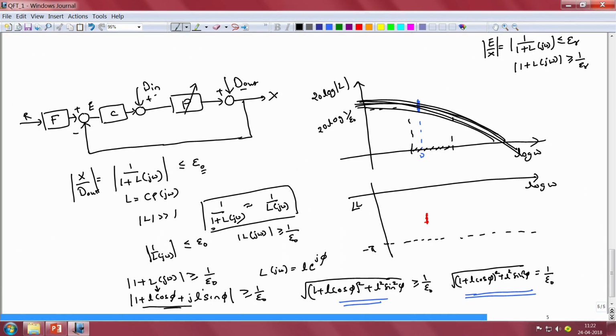The same thing also happens when we are looking at the phase characteristics. So, the nominal phase characteristics of the plant might have a single curve, but when there is uncertainty associated with either the pole location or the zero location of the plant, then these phase responses will also show a certain spread. So, for each particular permissible location for the pole of the plant you will have a certain curve, and similarly for each permissible location for the zero of the plant you will have a certain curve. So, once again the phase characteristics get transformed from a single curve to a bundle of curves.